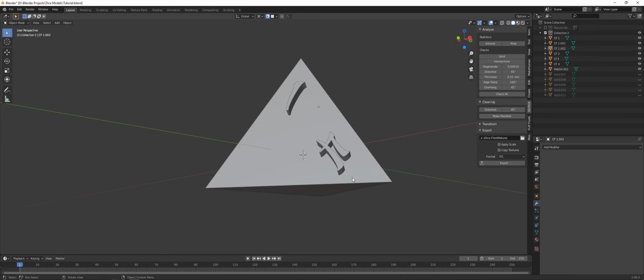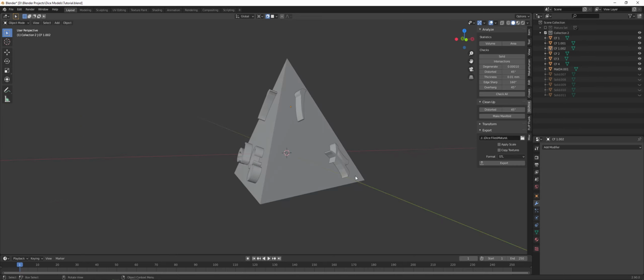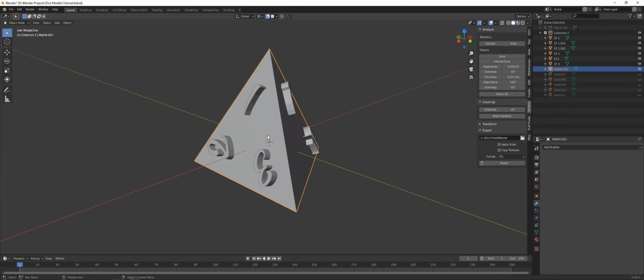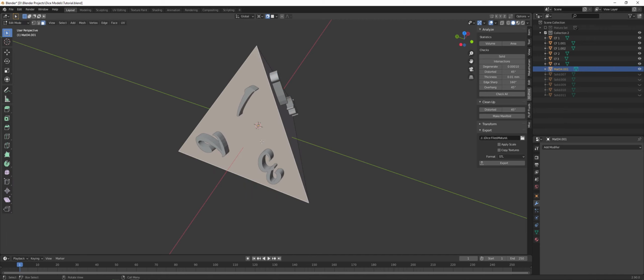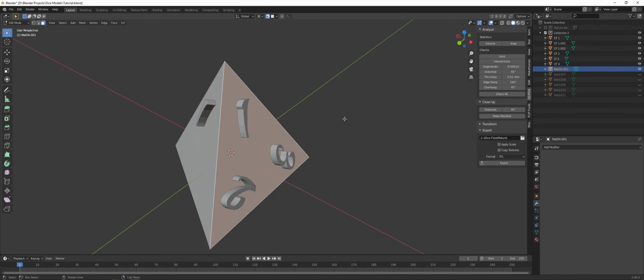You need an axis that is lined up perpendicular to the opposite face so that it goes through that corner. So how do you do that? You use the custom orientations that we talked about in the first part, right? So you go into edit mode, you select a face.